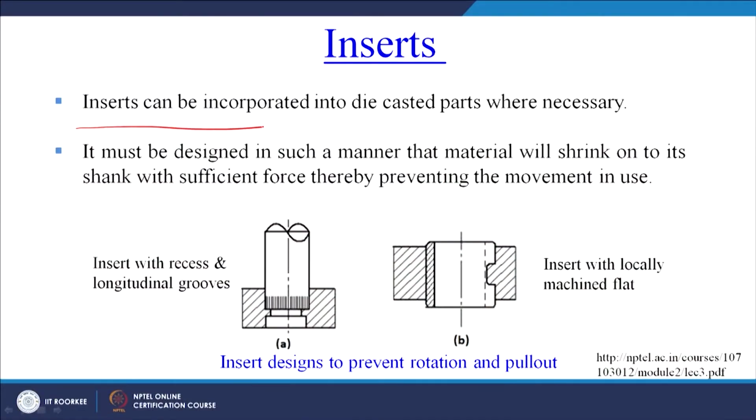Then once we have to put inserts inside our product, inserts can be incorporated into die casted parts wherever necessary. The inserts must be designed in such a manner that the material will shrink onto its shank with sufficient force, thereby preventing movement in use. So we have to ensure that the insert is properly jammed inside the metal when the metal solidifies.